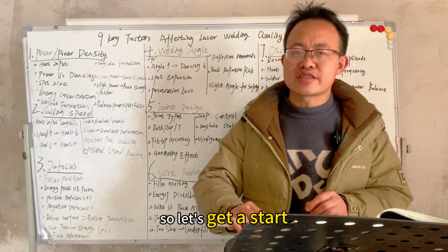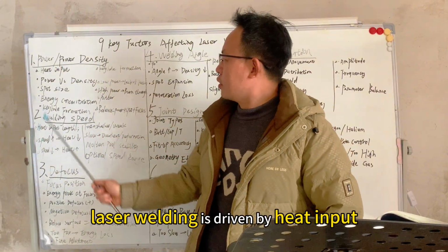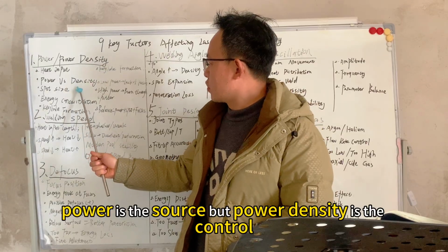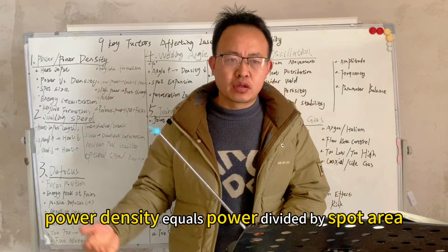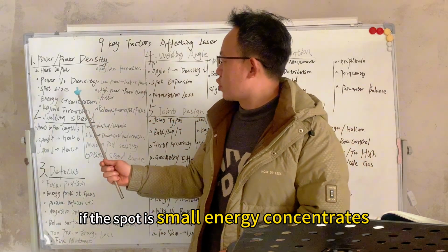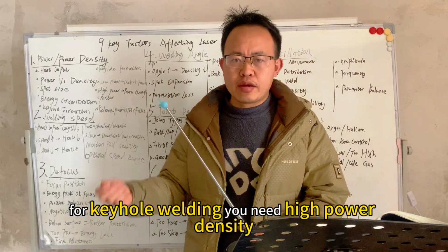So let's get started. 1. Power and power density. Laser welding is driven by heat input. Power is the source, but power density is the control. Power density equals power divided by spot area. If the spot is large, energy spreads. If the spot is small, energy concentrates. For keyhole welding, you need high power density.